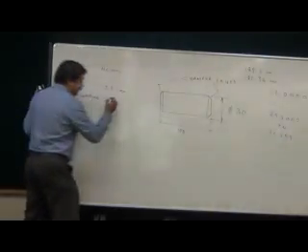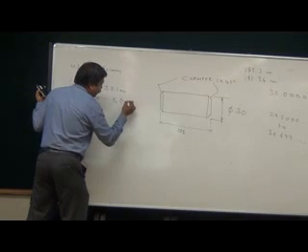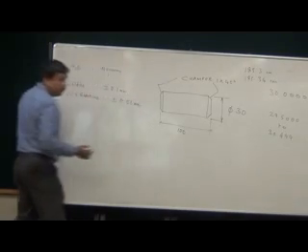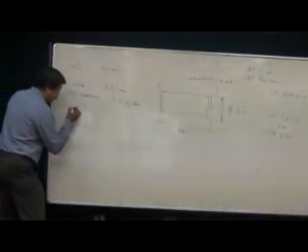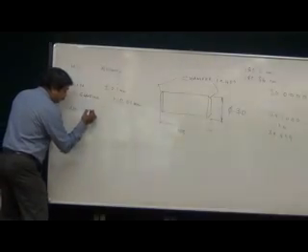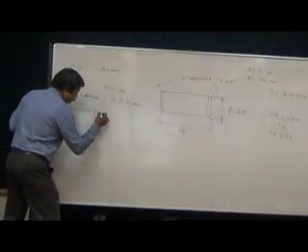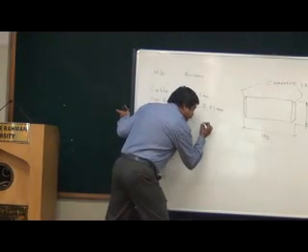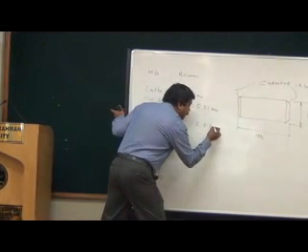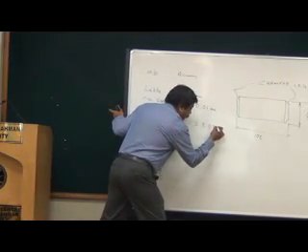If I do it in cylindrical grinding, I can get an accuracy of plus or minus 0.05 mm. See, there is another machine called centerless grinding. If I machine the same component in centerless grinding, I can get an accuracy of plus or minus 0.02 mm.